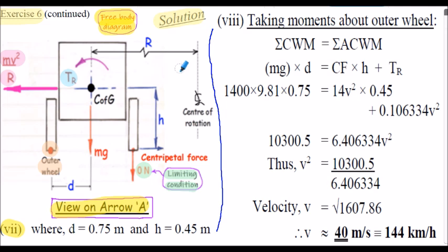The dynamic situation is the vehicle travelling around a bend at constant velocity whilst being subject to an inward seeking acceleration, centripetal acceleration. But we are going to analyse it statically, which we can do when we apply the centrifugal force and the inertia couple.